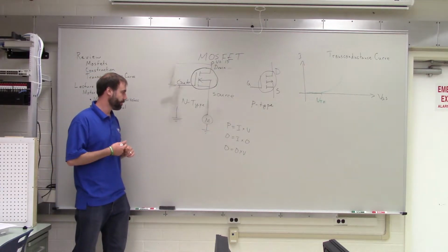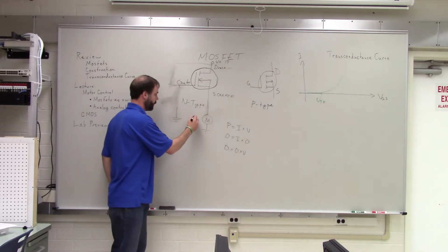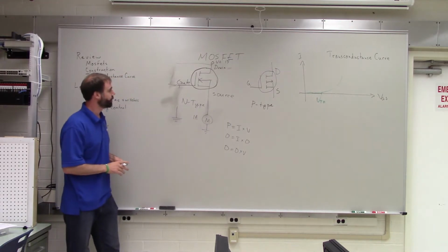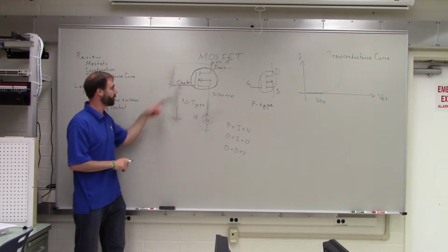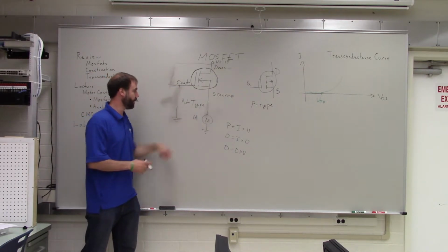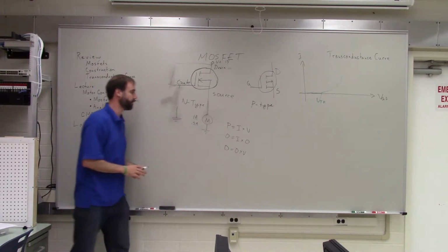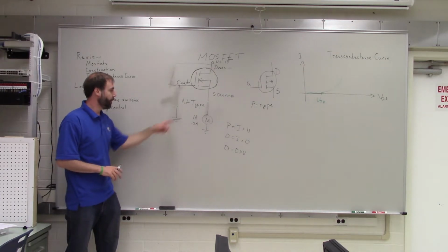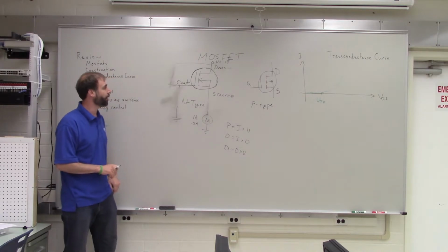So say this motor takes a maximum of 1 amp. So you could vary the voltage on the gate until you were getting, you know, half an amp down here, right? So that would control the speed of the motor, but there's a problem with that.